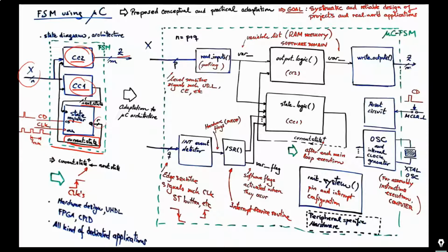And then you know as well that there are two special signals, very important, them both. The clear direct to reset the machine and the clock periodic signal that is for synchronizing the next state. So the current state next value is the next state here present in this signal and captured just when you've got clock's active rising edge.